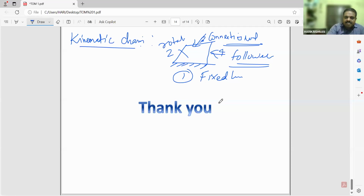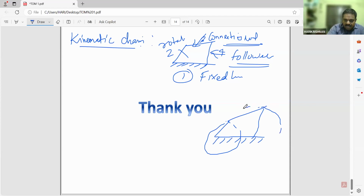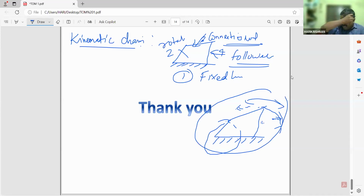When we connect the last link to the first link, there will be a definite motion that forms a kinematic chain. In this 4-bar mechanism, when it rotates, the connecting rod will move this follower to the left as well as right. Due to this motion, there is a reciprocating motion for this follower also. So this forms a kinematic chain. I think the concept is clear, what I mean by kinematic chain.